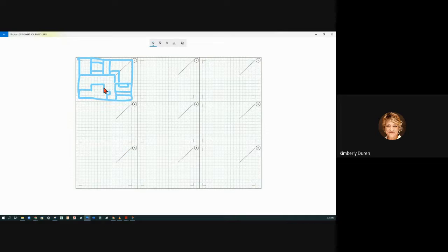So now I've got a hidden line right here. So I'm going to draw a little dash line. That's this edge right here. I can't touch that here. What else? I've got this plane right here. So this is when I use a ruler. I've got this edge. I've got that edge. I've got that edge. Oh, there's a corner right there. I'm going to go across and I'm going to make a hidden line over here for that back plane because it's not on the same height as this one.